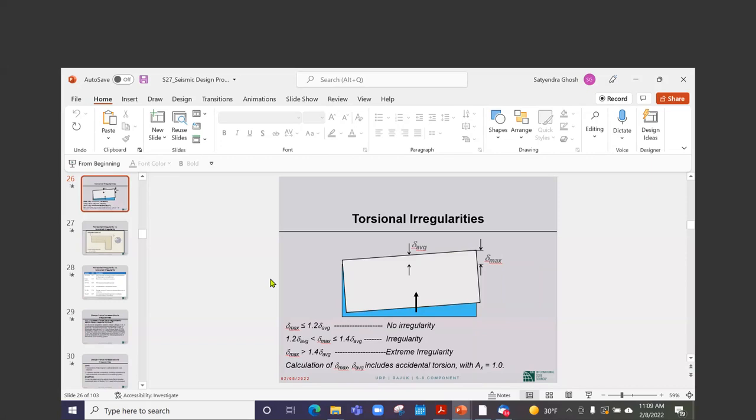To identify soil type like SD, SC, or SA in BNBC, we have to take the average SPT value up to 30 meters. However, if the standard deviation is very high, can we use the average SPT value? You should ask Dr. Abedin when he comes. I'm not the right person to answer that question.